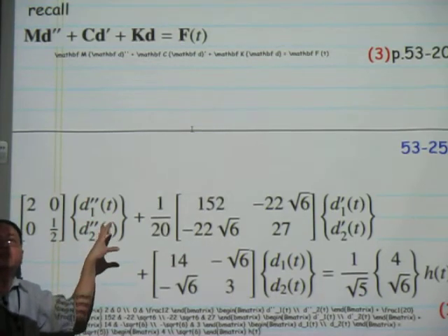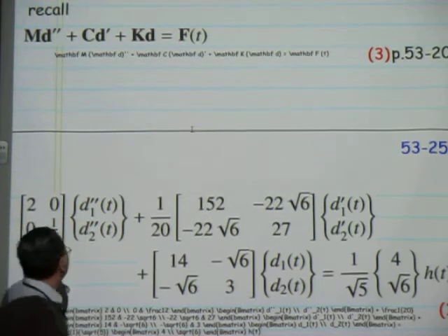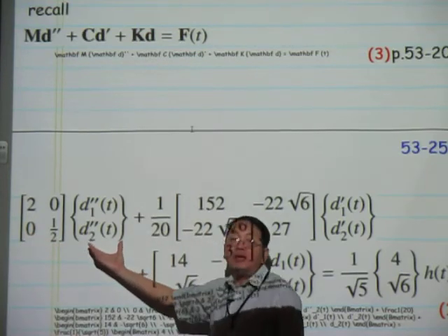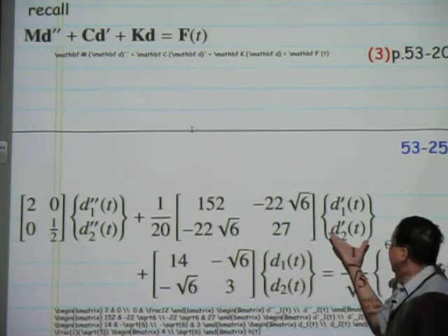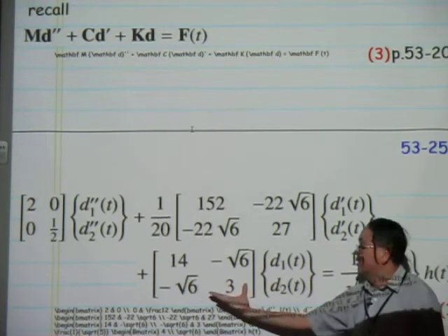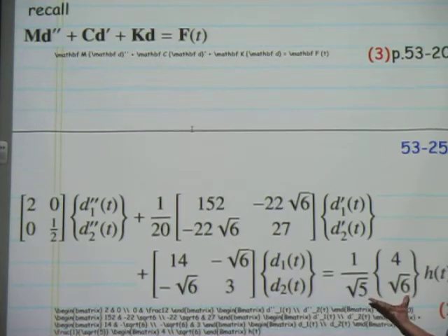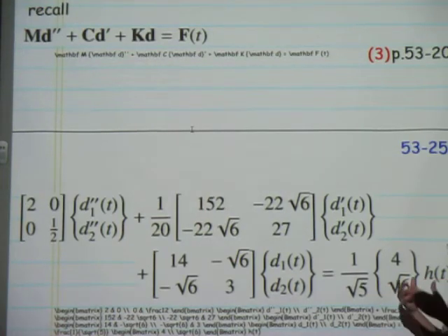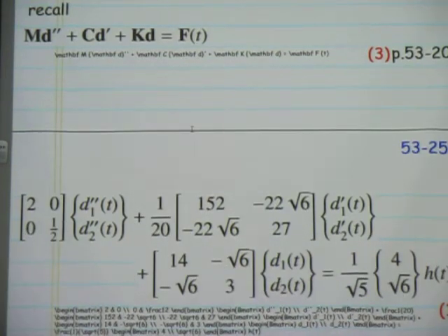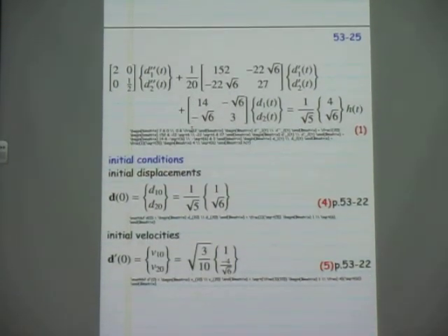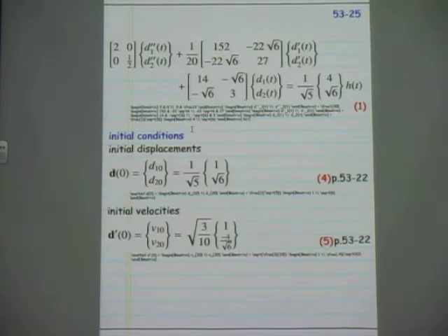This is also matrix form, but in fully expanded form, where you have the mass matrix, the matrix of the acceleration, the damping matrix, the matrix of the velocity, the stiffness matrix, the matrix of the displacement, and the forcing matrix, matrix of the forces, right? And h of t is a free time-dependent function where you can prescribe any function, right? Sine, cosine, logarithm, exponential, and that depends on the data of the problem. Okay, and so zoom out for the big picture, and then we zoom back in.